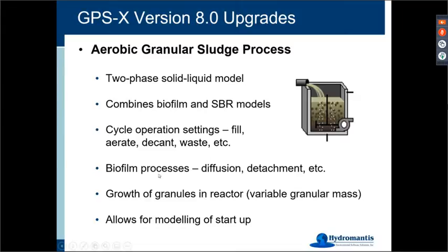As you'll see, it has a full biofilm model, but it's been modified in order to work for granular sludge as opposed to biofilm growing on a fixed surface area media. That's one of the aspects where we focused quite a lot on the development of this, is that granules grow differently than the way that biofilm grows on a piece of plastic that has a fixed surface area. So as the granule gets bigger, the surface area changes and so on. So that needed a bit more sophisticated model than the way that we would do it.